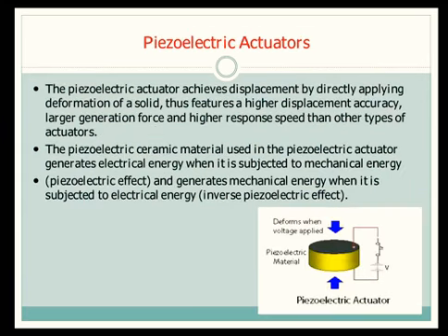Next is piezoelectric actuators. It achieves displacement by directly applying deformation of the solid, thus features a higher displacement accuracy, larger generation force and higher response speed than other types of actuators. A piezoelectric ceramic material is used in the piezoelectric actuator, which generates electric energy when it is subjected to mechanical energy. Any material called piezoelectric material generates some voltage when it is applied with force.